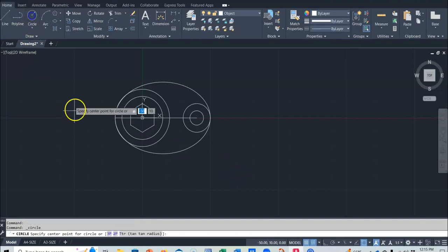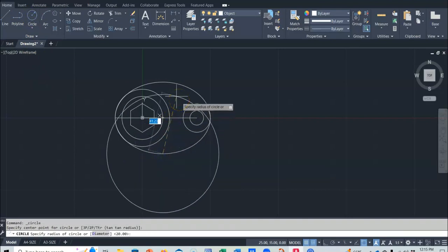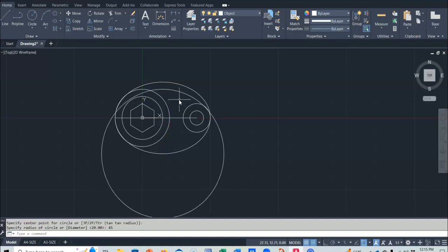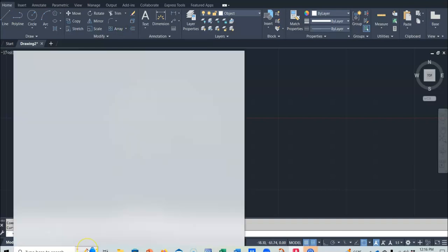And then the next choice is this circle where we drag it out. And if you see, it has a dimension of 45, a radius of 45. It shows that twice. So I'm going to put that radius in, boom, and there's our circle, right? Now, exactly how to do the next step can be kind of challenging. I'm going to use what is known as the fillet command, right? You know, there's 4 fillets here, right?